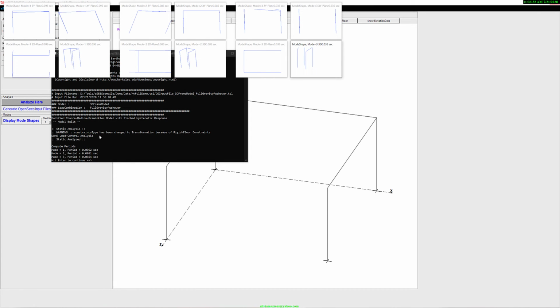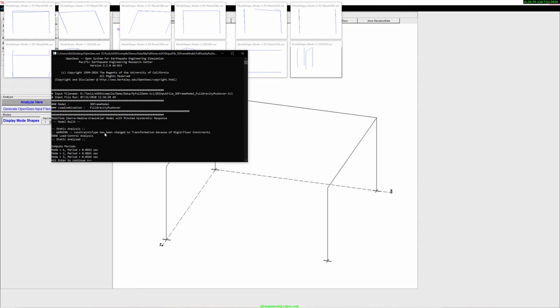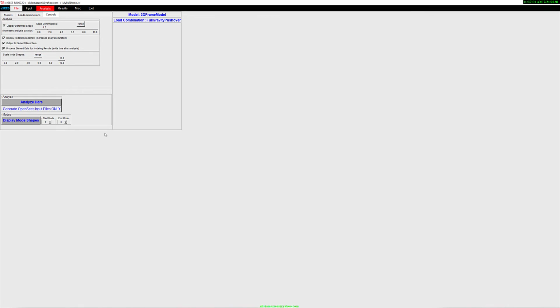Here is the second load combination. Pushover has the same gravity loads. So what I do is define the masses and perform a gravity analysis, and then perform an eigenvalue analysis, because that's really where you want to be: what are the properties of my structure after gravity is applied, but before any sort of lateral load is applied. So I'm happy with this. I click on the OpenSees window and close it.